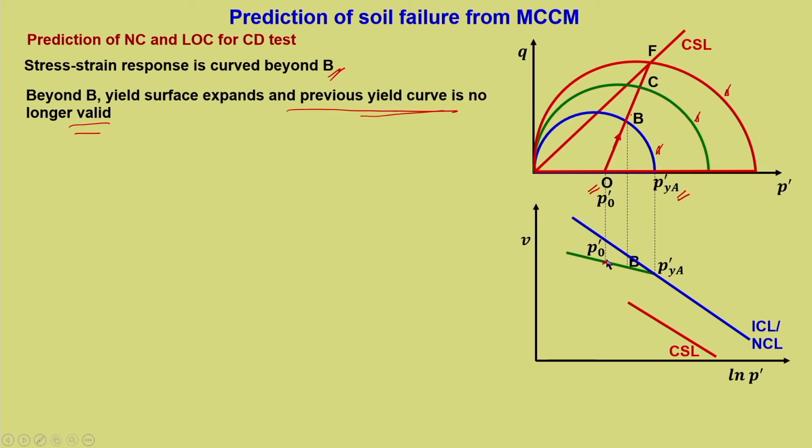and when it is loaded, that is from the point O, I can also write here it is point O. So, from point O we know that up to here it is elastic response up to B. Then if it is elastic response, it cannot deviate, but it has to move along the green line. Why? Because we know that the unloading reloading line is an elastic response. So, we can easily take it to be along OB. That is what is marked, and this is the same thing we have seen in the previous slide.